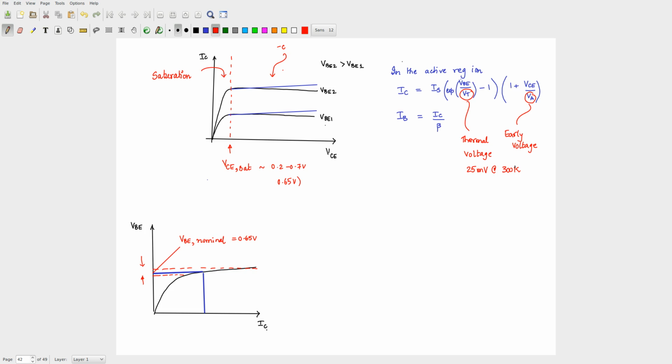Yes, there is one other thing that we should keep in mind, that if you look at this kind of circuit, again because the current is exponentially dependent on VBE. If you were to make this kind of plot, you will have VBE 1 as 0.65, VBE 2 will be 0.66, things like that, right, because even for very small changes in your VBE, you will see significant change in your current. So, what people do is to not plot it like this, but rather think of a biasing arrangement, something like this, right. I have my BJT like this.